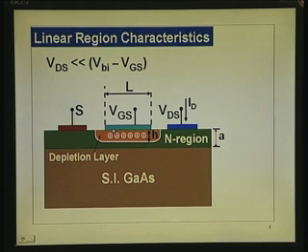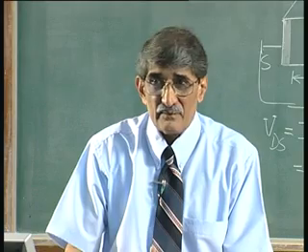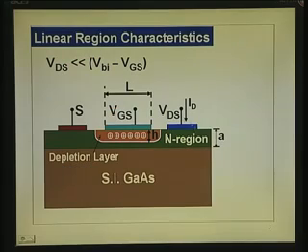Now, due to this metal semiconductor contact, what do you have below that? The height, thickness of this n layer, I put as A, similar to what we put there, and the depth into this plane we have taken as W. In all the analysis, we call this n region a channel, because it is the region in which the current flows. So channel length is L, the same terminology used in the case of MOSFET. Channel width is W and channel thickness is A. It is this A that you are controlling by applying voltage to the gate and source.